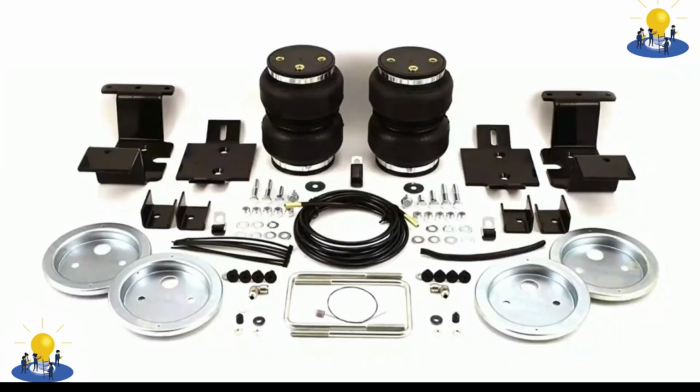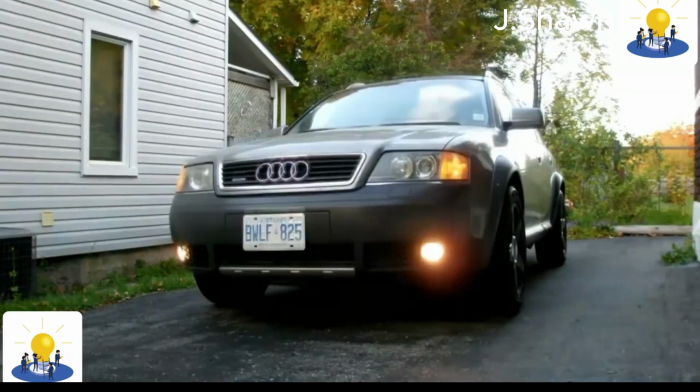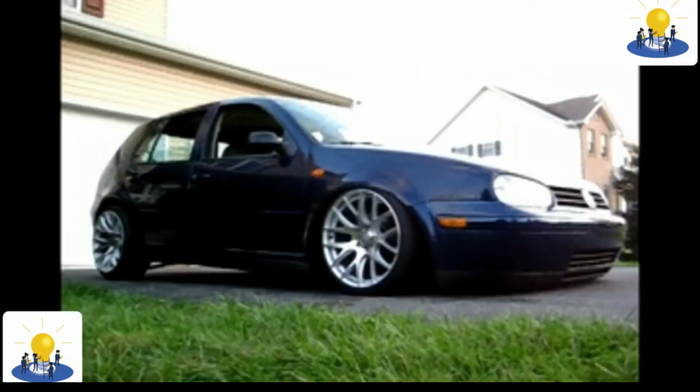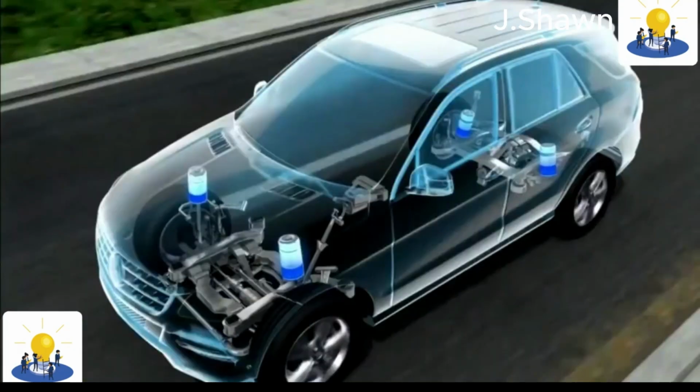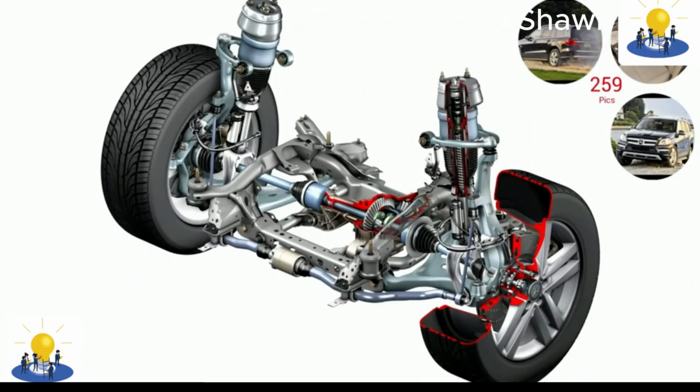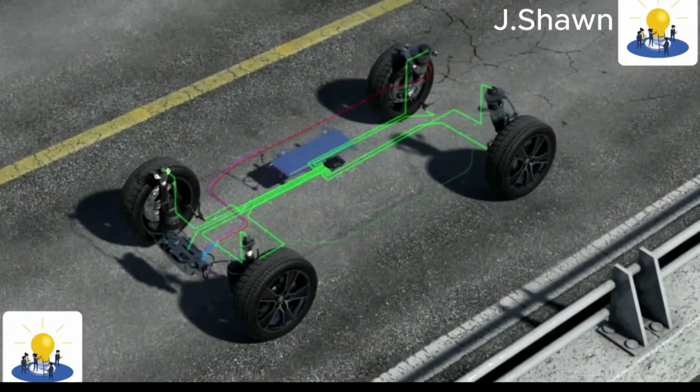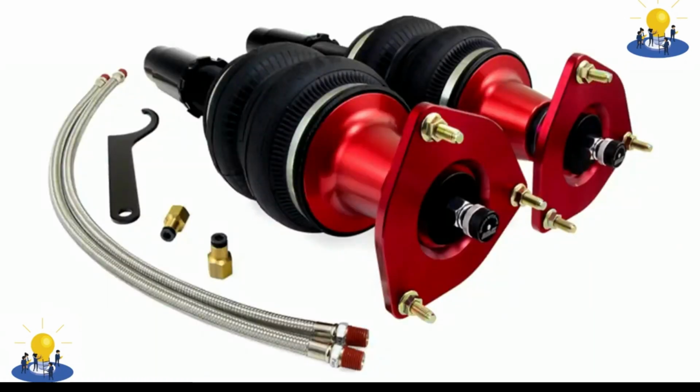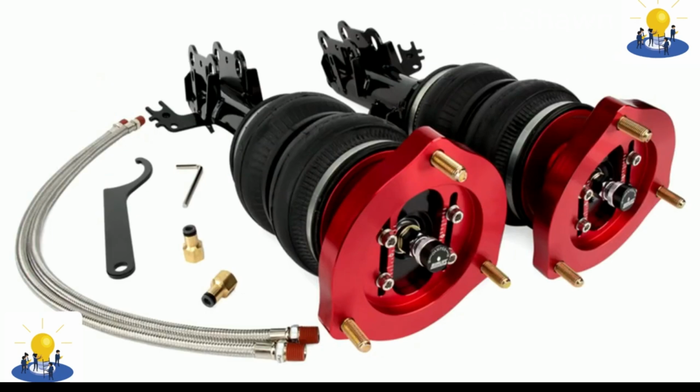This mode of failure will typically take some time to occur after the initial installation of the system, as the integrity of a section of airline is compromised to the point of failure due to the rubbing and resultant abrasion of the material. An airline failure may also occur if a piece of road debris hits an airline and punctures or tears it, although this is unlikely to occur in normal road use. It does occur in harsh off-road conditions, but it's still not common if correctly installed.